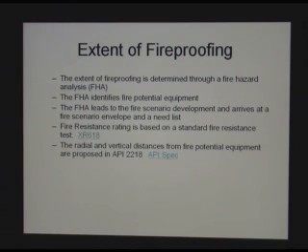Typically all structural steel or vessel supports which are located in this fire scenario envelope require fireproofing. The fireproofing is based on a fire resistance rating. You determine how many hours you expect the steel has to last in a fire case.